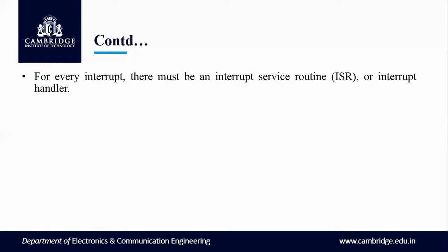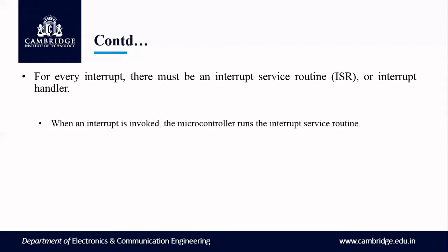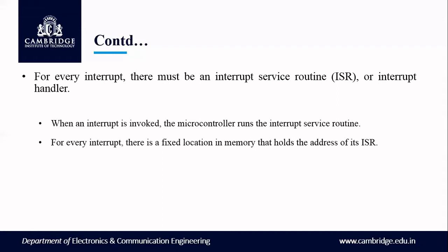For every interrupt, there must be an interrupt service routine or an interrupt handler. When an interrupt is invoked, the microcontroller runs the interrupt service routine. The interrupt service routine is a task, a set of instructions written for servicing that particular interrupt, or a particular job to be done by the microcontroller. So that will be written as a subroutine.